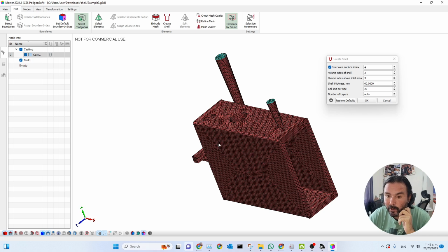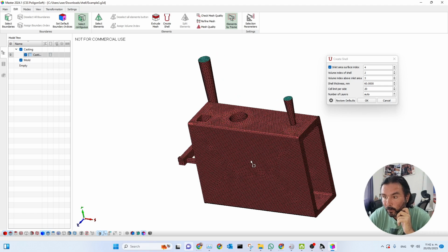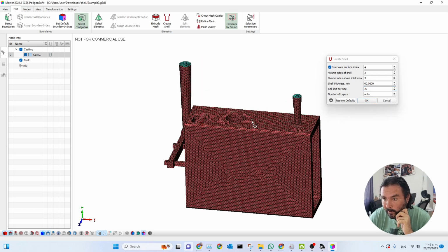And even if we have 60 on this side, then we put a virtual mold and the heating will be correct. And the last parameter we need to assign is the quality of our mesh. This parameter isn't very obvious because the numbers are quite random. The minimum quality corresponds to the number 20, which is what we need to set. The maximum quality corresponds to 150. Since we need to get the coarsest mesh possible, we put 20, and now we can execute the command.